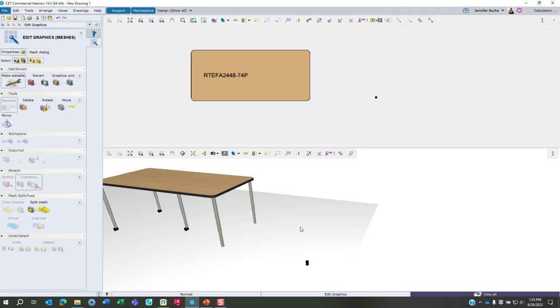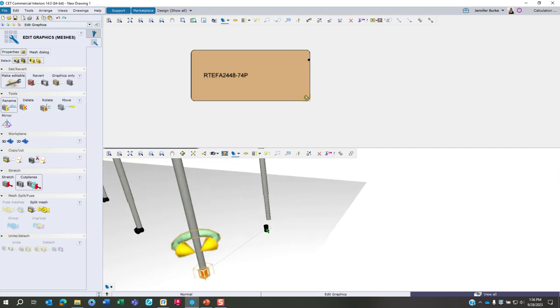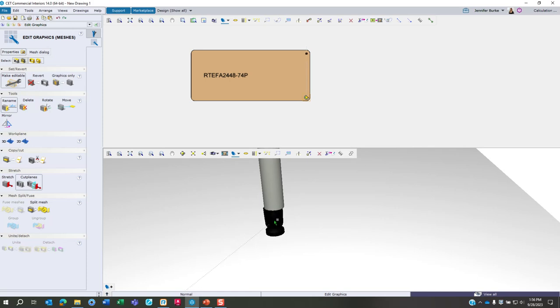We now need to move that glide in position. One way you can do that is select the glide and use the move tool on the left-hand side. The reason I had the other table snapped the way that I did is that was 48 inches wide. What we could do is use the move tool, select the glide, and use the arrow to position, and then type in 48. That was the width of that desk, and it moved over directly under the post leg. And then the next step I would recommend is hitting the letter A to copy. And if you did know the exact distance, definitely use that, or you could eyeball it.